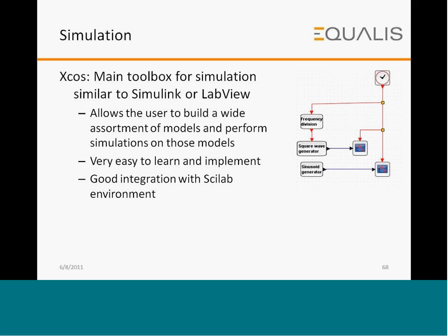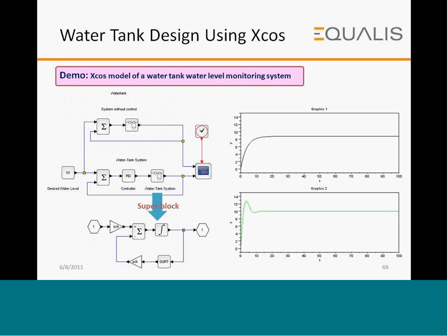One of the toolboxes which is very powerful in Scilab and that's similar to Simulink and LabVIEW is XCOS. Say I have a water tank model that I want to build using XCOS to simulate and understand the behavior. I can build a model like this. As you would observe, you are not writing a script-based program, you're building a model which is very intuitive. The program gets automatically generated in the background.